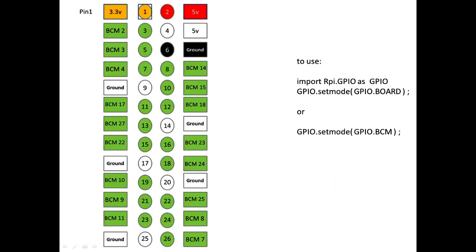So as we said, we're using the GPIO pins on the Raspberry Pi, and we can see those numbered from pin 1 all the way through to pin 26. 2 slightly different variants here, depends upon whether you're using the chip settings. So that'll be the BCM or Broadcom chip, and they are identified as the BCMs 2, 3, 4 and so on.